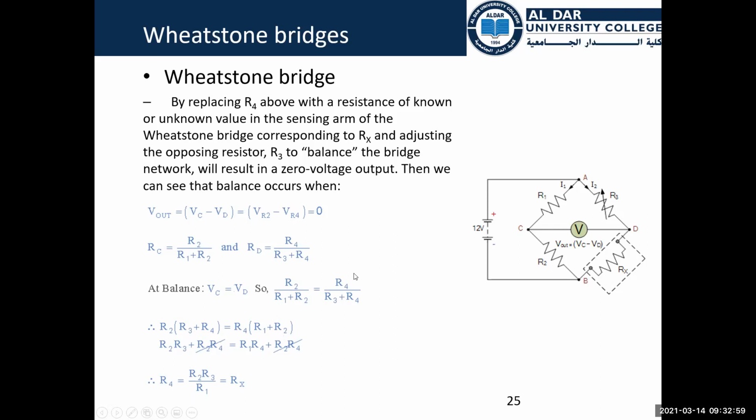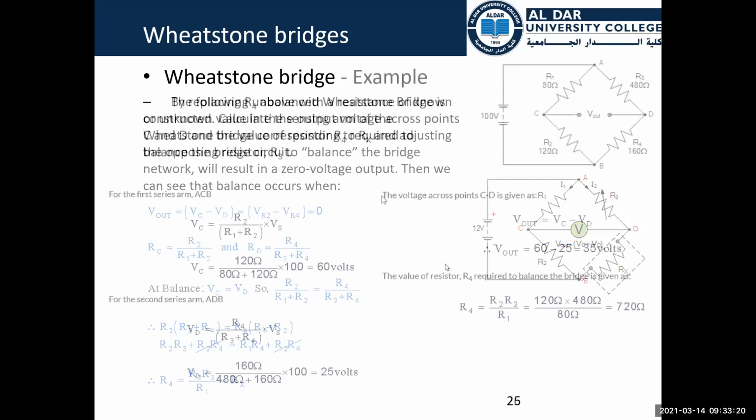This is the way to balance the Wheatstone bridge. Balancing it is important, as I told you. If you stand on a scale and want to measure your weight, you have to zero the scale first before starting measuring. We do that using this equation.